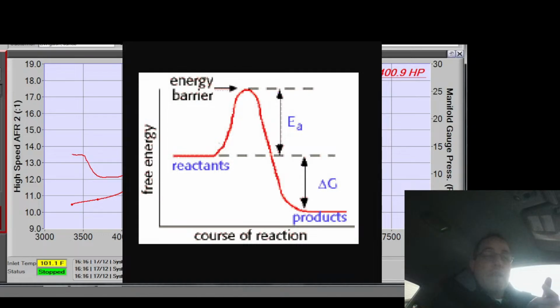And the other thing, too, is that when molecules are moving past two electrodes, it's more difficult to ionize them because they're moving, and you're getting fresh ones in the way. So the more turbulent the cylinder is, and the more horsepower you have, and the more overlap flow, the more turbulence you have in there, the more spark energy you need because everything's moving around a bunch. Anecdotal,